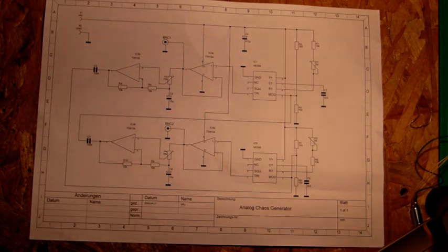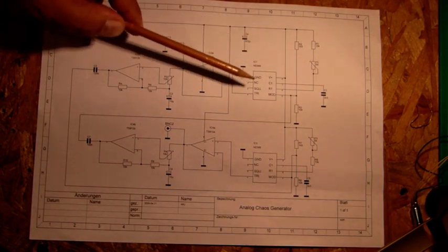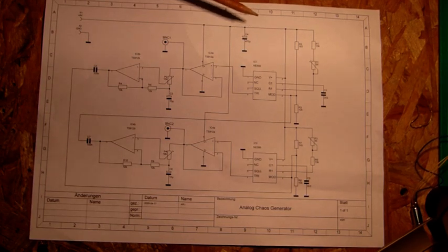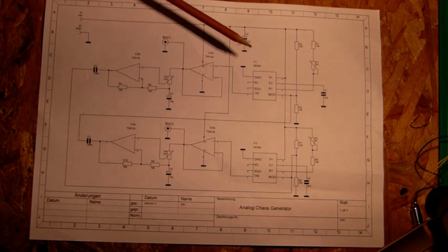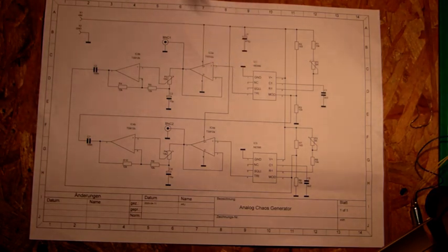The reason is that you can't do sweeping operations with a rectangular waveform. This is because a rectangular waveform is specified by jumping forth and back between 2 different extreme levels, and so you don't have all those values in between. This is not suitable for a sweeping operation. For this reason I chose the triangular wave output.